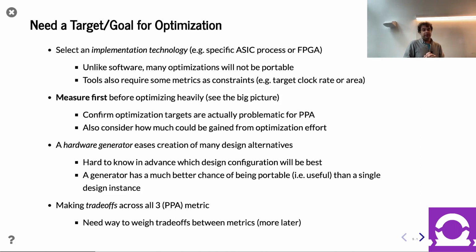To your point about the clocks, yes. It's now a basically almost mandatory optimization, but 20 years ago was considered novel. Clock gating can now be done pretty reliably by some CAD tools if you get the right combinations of features and the right CAD tools. So what does that mean from the Chisel point of view? There are some small considerations about which kind of registers you use in certain cases, to make sure it's possible for the CAD tools to do the clock gating for you automatically. You don't want to be doing clock gating manually. You want the tools to do it for you.